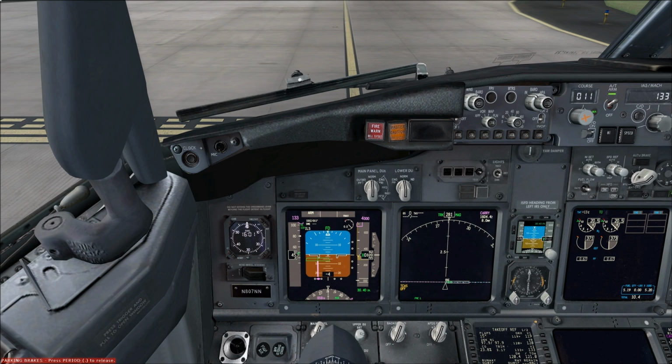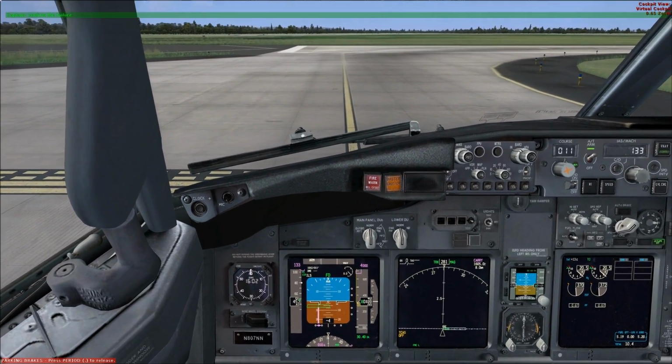Now as the radar emits the microwaves and receives any reflected signals that may come from water droplets in the air, this is analyzed by the PWS, or predictive wind shear system, using some sort of Doppler algorithm, and determines based on the movement of the water droplets if wind shear is present. It doesn't work in totally dry atmospheric conditions. It may work on dust particles, however, I've read that this may cause false indications of wind shear, which is why it's always good to confirm if there are any pilot reports or look for any other signs of wind shear.